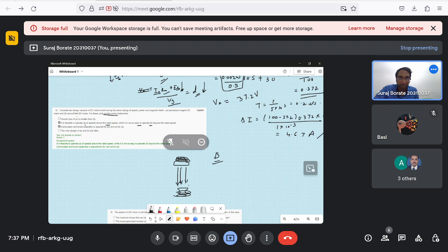It gives a circuit for the reverse current to flow, so even when the switch is off, this is possible. It ensures that the current in the inductor is in a closed path when the main switch is off.